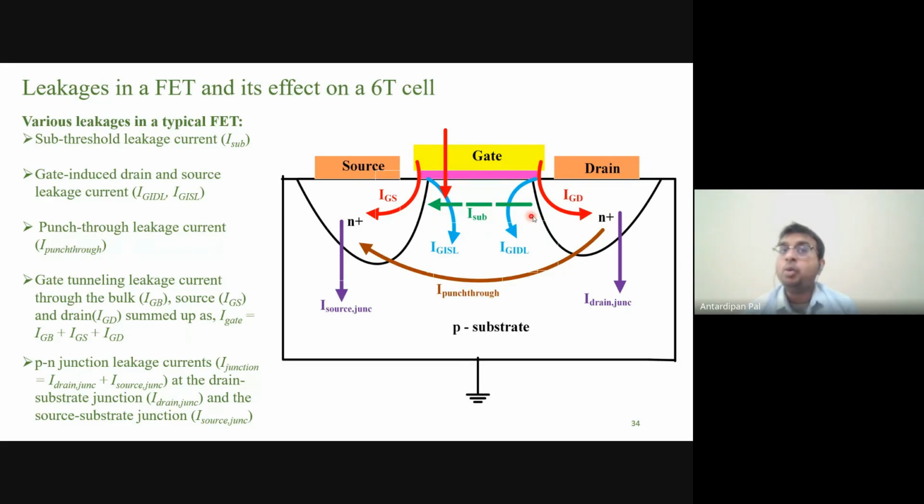This will be there, which is equivalent to the dark current. Remember in the output characteristics, we had the dark current. What's the dark current? When the light is not shined on the nanowire, no external carriers are generated. But we have the drain source voltage. That's the dark current. That's equivalent to the sub-threshold current. So only the one with the green arrow, this leakage, will be present. Other leakages are totally gone, no question, because of the structure of the device. It's a different structure. It's a different device physics.